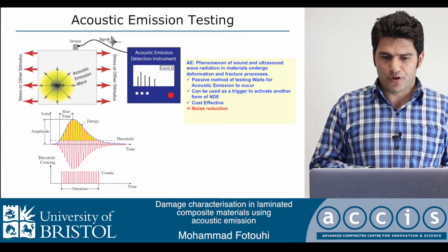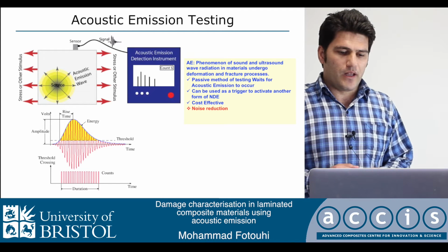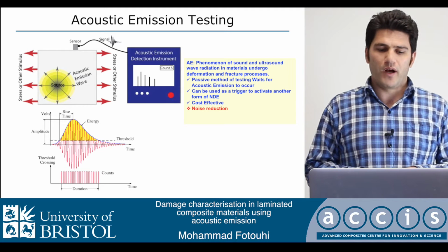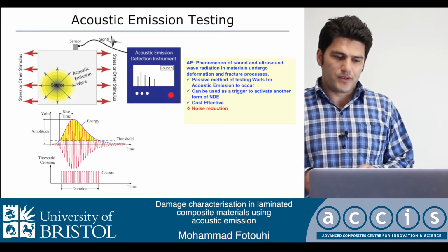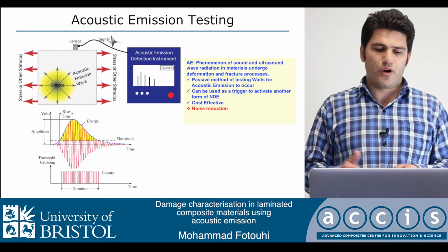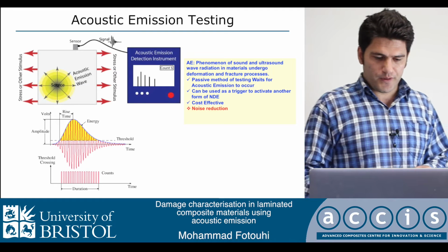As you see from the picture, we have a sensor. We are catching the waveforms, and later we are analyzing them using special software. Each waveform has its own parameters, like amplitude, rise time, energy, and other parameters.